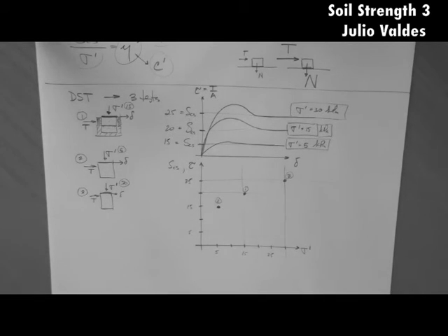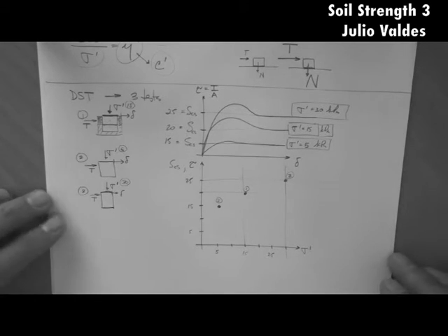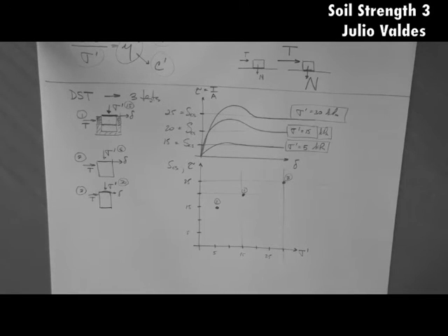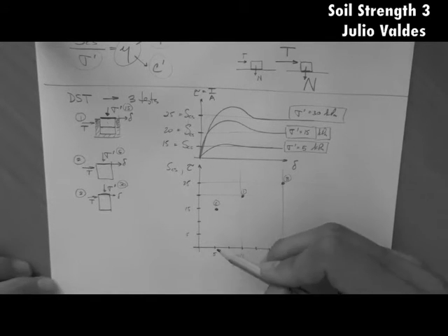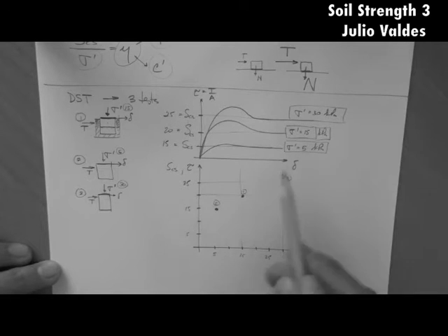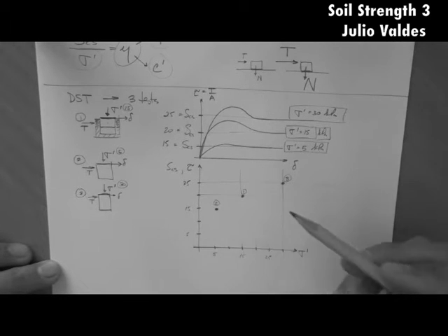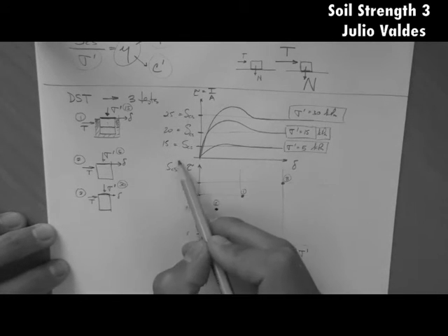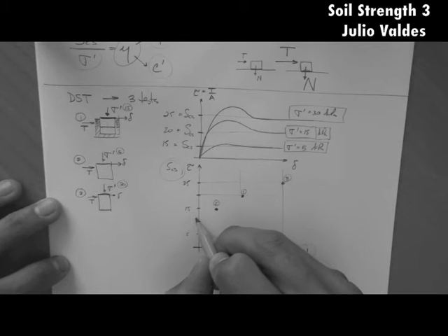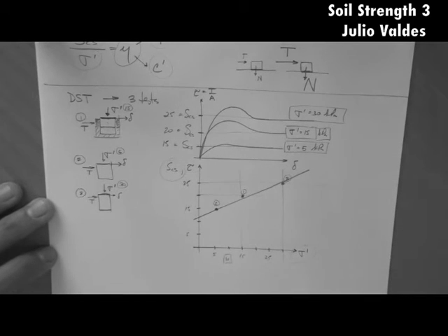Okay, so we have 3 points in the Mohr circle space. Now, what we do to get the relationship is we look at the points and we realize that, for a rough approximation, they fall on a straight line. So, look, if we apply a stress of 5, we get 15 as a strength, which we did, right? Of course, it's a point. If we apply a stress of 15, we get a strength of 20. If we apply a stress of 10, we may get a strength of about 17, right? So we are basically saying that the relationship between the stress and the strength is denoted by a line, which we as engineers decide to create by best fitting the points.